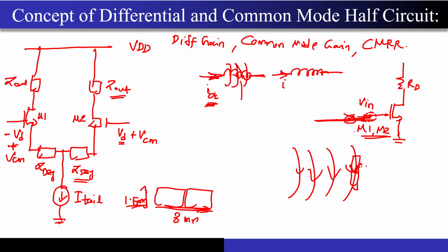to reject this interference? The best way is to replicate this circuit and take the input as differential, so that the same interference, same noise, the voltage that is getting generated because of the time varying magnetic field, will be present at both these inputs. And when I take the difference, if I get the output which is, let's say, proportional to A, the constant, times Vin plus minus Vin minus, then this interference that is generated within my own chip will get rejected. So that is why we are working with differential circuits.